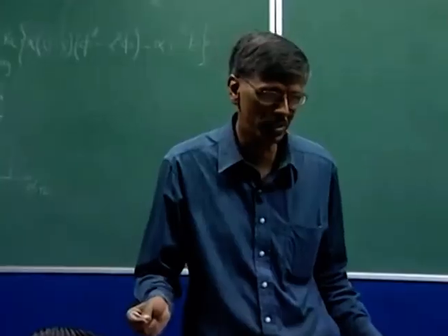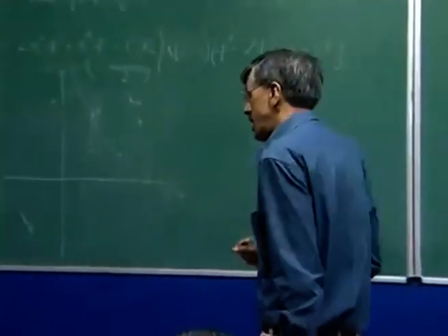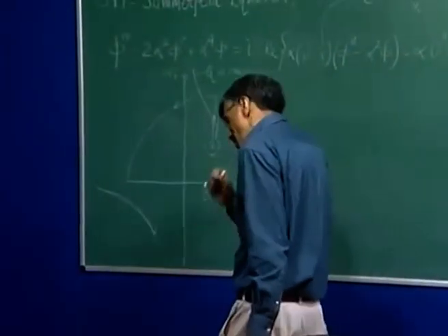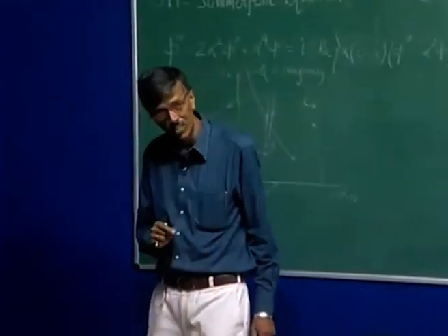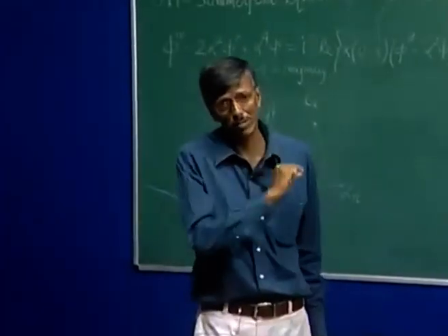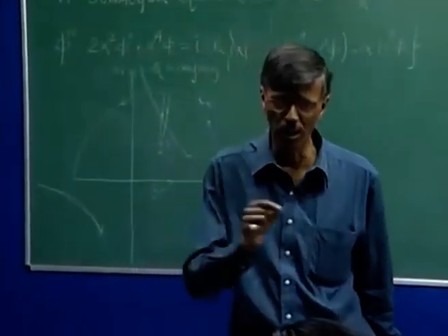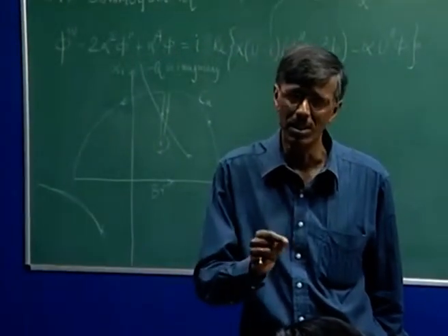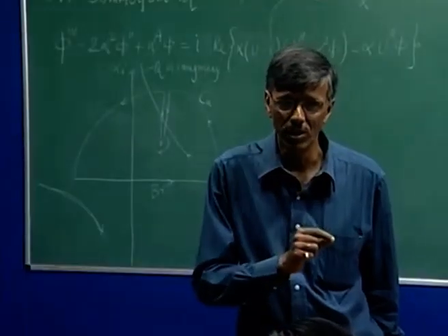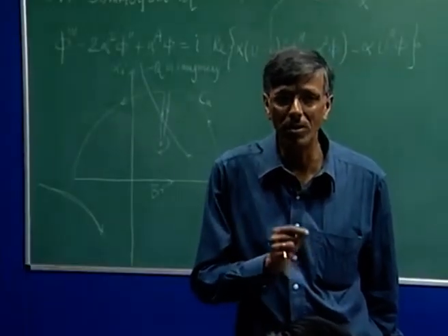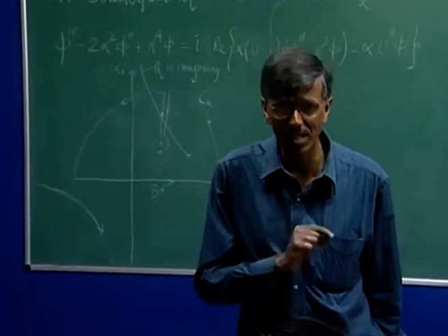That's your regular perturbation theory. In a singular perturbation theory, like the boundary layer theory itself is, the highest derivative term is multiplied by the small parameter. And if we try to go through the regular perturbation theory analysis, then we see that we are not able to satisfy all the necessary boundary conditions.